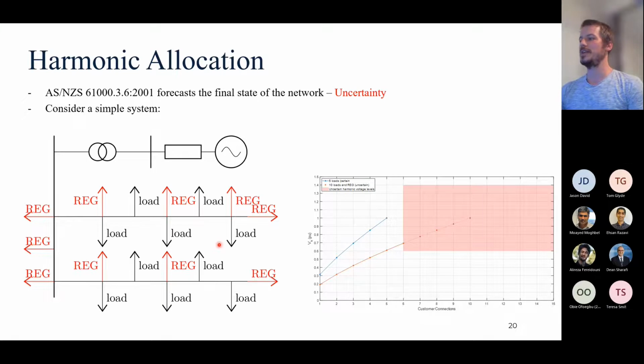And so now we're in this area of uncertainty. I say uncertainty because, as I've just mentioned, if we knew that this was coming, then to all of the loads that had come earlier we would have allocated a smaller amount, but we didn't. So now it's very possible that we could be operating at a very high level where our planning levels are exceeded. Now that goes against exactly what I presented 10 minutes ago with distortion levels and what they're doing, and that's completely fair, but we're at the start of this.